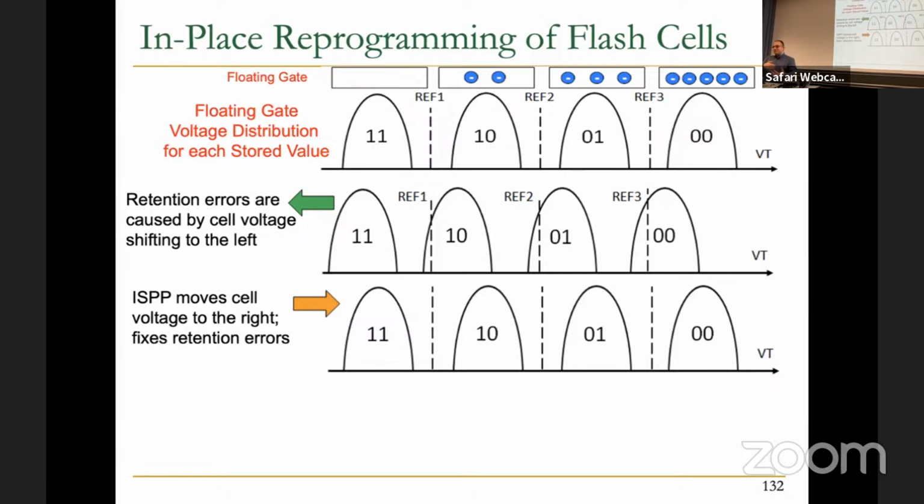When they want to reprogram, they can just increase the threshold voltage again and move to another 4 steps. With that, they can control more, essentially, and then they can reprogram. But the issue with those works, and also this work, is the program interference effect that we discussed. We need to obey the order of programming. So once you program a page, you need to go to the next one.